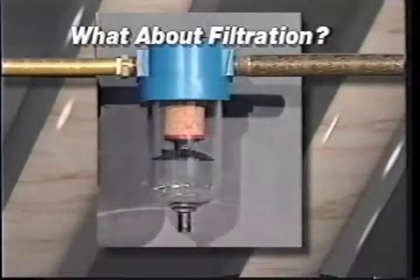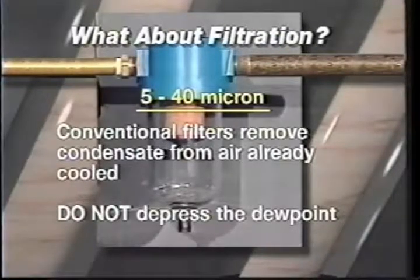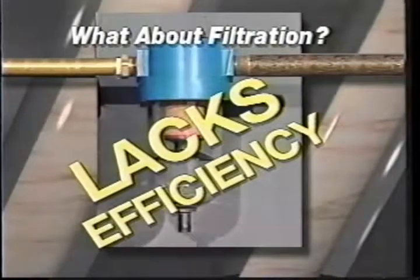What about filtration? Conventional 5 to 40 micron filter units help to filter and remove condensate from air that is already cool, but they don't depress the dew point. More condensation may occur downstream as air cools further. These commodity filters generally do the job for which they've been designed, but in today's sophisticated environment, many applications require greater efficiencies. These conventional filters are just not efficient enough for many of today's tool and instrument applications.